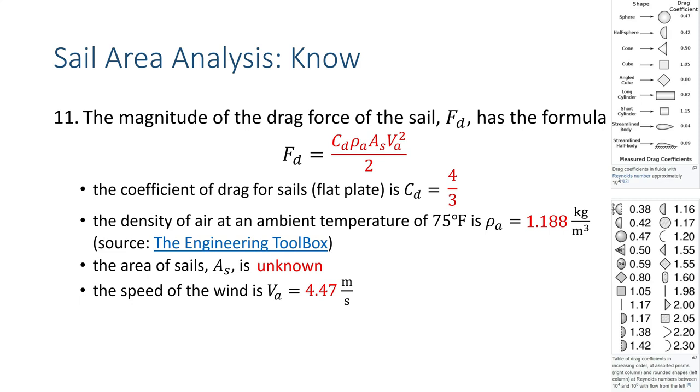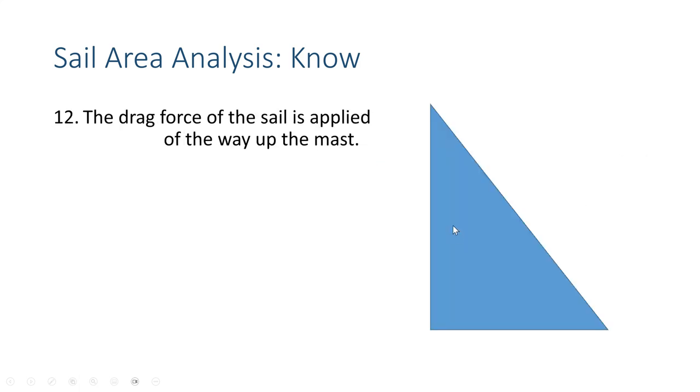We've got our sail fully extended and it's just catching as much wind as possible. And it will deflect just a little bit, right? And so that's why we're saying it's a little bit better catching wind than just a flat plate. Because it's going to deflect a little bit, but maybe not quite as much as what we're seeing here in this semi-elliptical head. So that's why we say about 4/3. So that's our drag coefficient is 4/3.